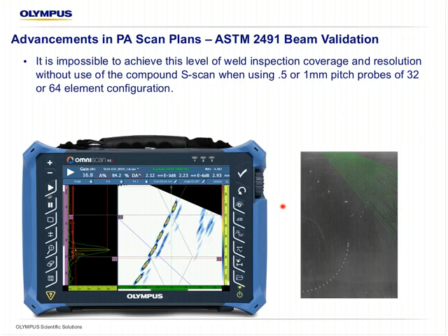And again, the other thing this block does is it separates pretenders from contenders. It also helps us identify extraneous adverse echoes from the wedge and housing and indications as well. It's very, very useful, and I highly recommend it. These are available in carbon steel and common austenitic materials as well. And for phased array, they're a very big help, especially the 30-degree weld bevel.